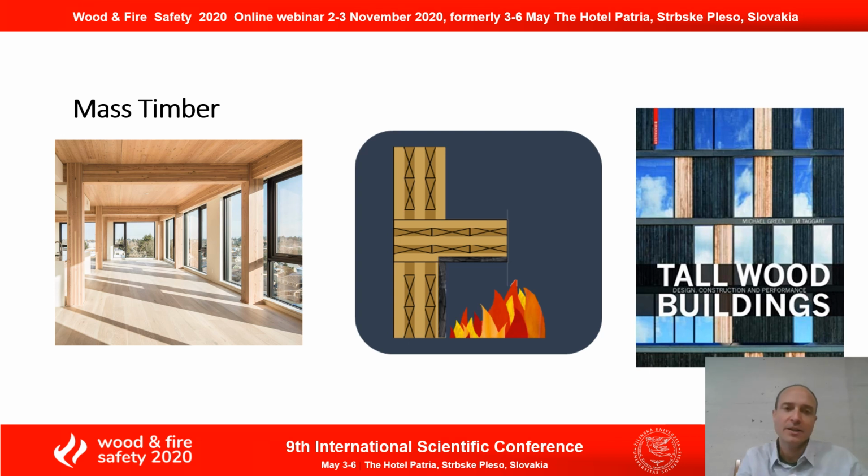So mass timber, there's kind of been a revolution of mass timber use in the United States. I have another talk about that in North America, but it's a class of wood composites that includes cross-laminated timber, or CLT. So those are big panels that come with dimensional lumber glued together in alternating layers, and they can come to the job site with doors and windows pre-cut. So that's kind of what's on the ceiling in this picture here on the left. And then it includes glue laminated timber, laminated veneer lumber, other types of structural composite lumber.